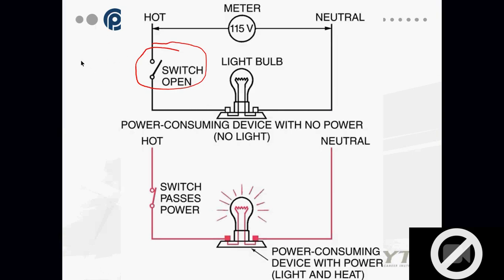Tell me a little bit about if I am taking a voltage reading from here to here. OL? Okay, volts, what am I going to get? OL, right? You're going to get 15. You're going to get the source voltage. Yes, I'm going to get source.